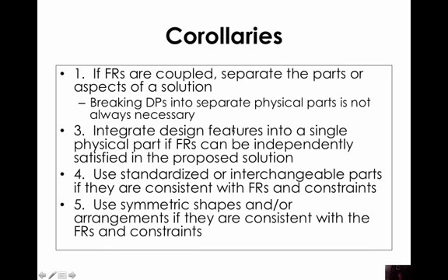So in other words, if the design doesn't get too unwieldy by specifying distinct design parameters for each functional requirement, or more specifically, if the design doesn't get too unwieldy by specifying distinct mechanical components for each functional requirement, then we actually want to do that. But again, it's not always necessary, as that first corollary states.